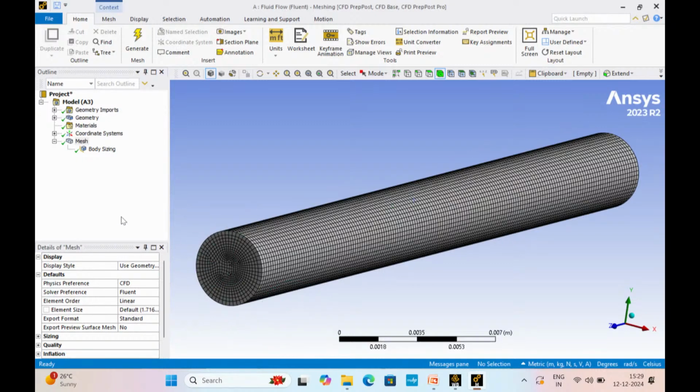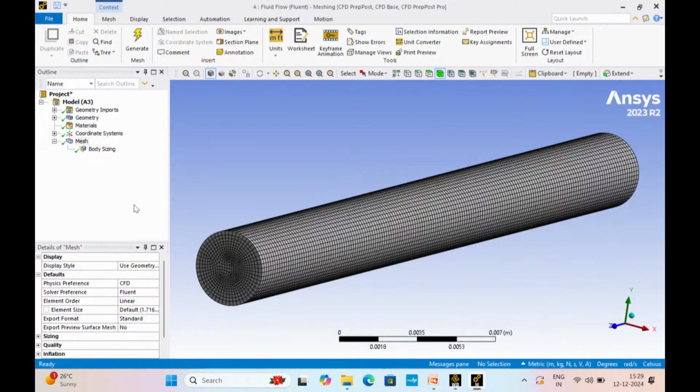So you know the reason why we need the finer mesh near the wall, because of all the gradient there. If you want to capture that, we need a very fine mesh. Anyone who has not yet completed up till this?